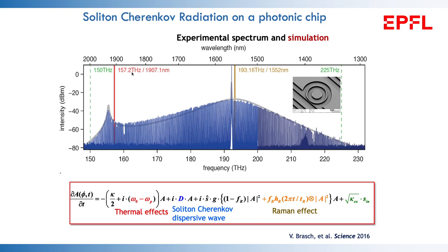In general, because it is a nonlinear process, and also when it is generated it involves a large resonance and laser tuning, the conversion efficiency from the pump power to these comb lines is fairly low. For example, it's typically less than 1% for the 100 gigahertz comb line spacing in this case. So in any application of this optical frequency comb, you really need to use an EDFA afterwards.